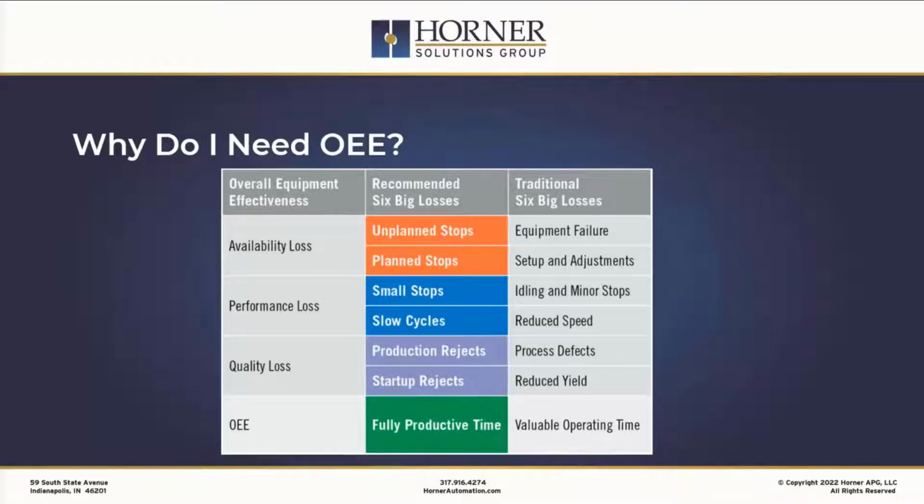Why do we need to do OEE? It really comes down to the big 6 losses. This is a term that's used out there for anybody that looks at OEE and evaluates what OEE is all about. In the traditional sense, it's about equipment failures, the setup and adjustments that are made on a machine, minor stoppages and idle time that are taking place. Maybe your work cell has a reduced speed playing in. And then there comes the quality side of it, which gets into the defects, or material not being available to make the right product. It's not the right thing being made.